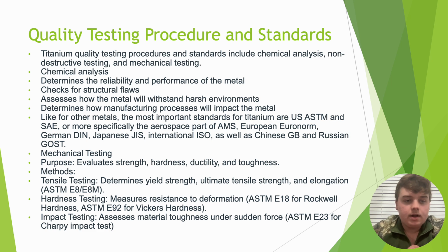Like for other metals, the most important standards for titanium are US ASTM and SAE, or more specifically, the aerospace part of AMS, European Euronorm, German DIN, Japanese JIS, International ISO, as well as Chinese GB and Russian GOST. Mechanical testing. Purpose: this evaluates strength, hardness, ductility, and toughness.